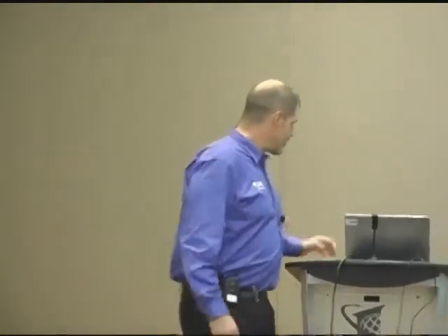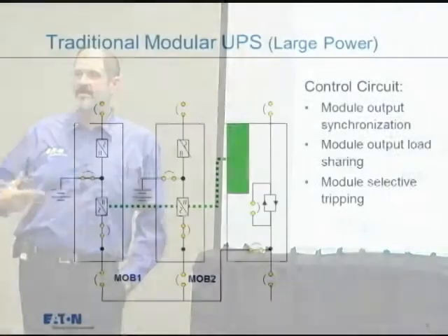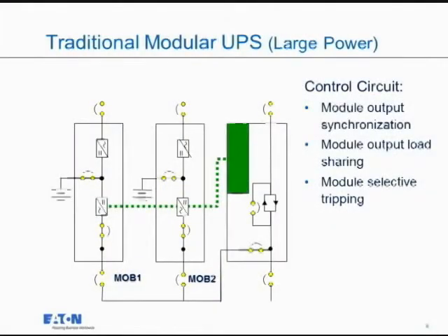But really, fundamentally, a UPS module is basically incoming power rectified to DC to feed a battery to keep the battery charged, but that DC power is then inverted back to an AC to create clean, filtered, regulated, perfect, guaranteed, 100% pure power to you on the inverter output. When I parallel 2 inverters, I need to really worry about 2 key things.